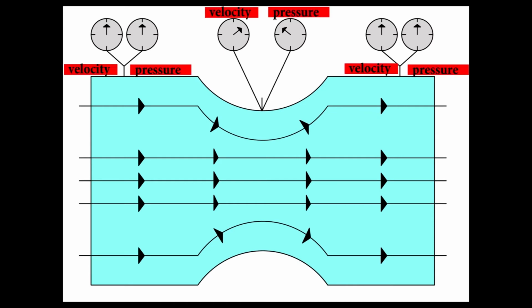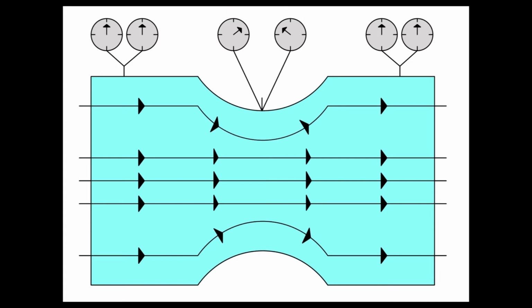As soon as air enters the constriction, velocity increases and pressure decreases. Once the air leaves the constriction, velocity decreases and pressure increases. This is how Bernoulli figured out that there is a pressure difference when air passes through a constriction. The upper part of the aerofoil acts as a constriction.